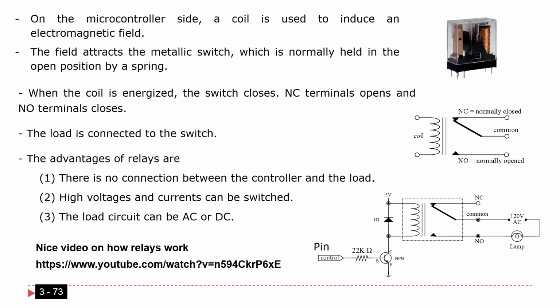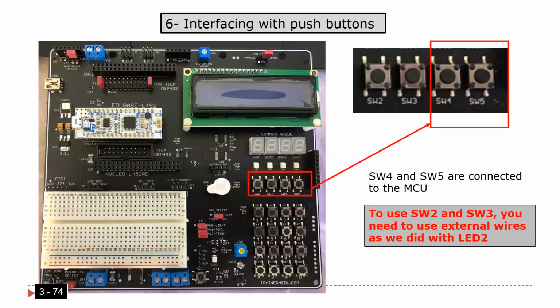So far, guys, I gave you one example: how can you program one output device? The output device is the LEDs. We have 4 LEDs, okay? I explained them. So now I'm going to explain how you can program an input device. You should understand, as I said before, the difference between an input and an output device. Here, this is a microcontroller. If this one is an output device, then using code, the microcontroller is going to put here 0 volt, or you can put here 5 volt. Is that okay? That's what we actually did.